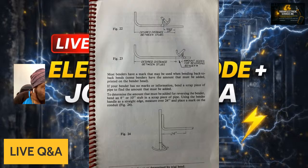Measure over 24 inches and place a mark on the conduit, figure 24. So again, it's basically telling you, most of us who've been bending conduit for years, on a simple offset, we can look at the bend that we need, the distance, and we can almost tell how much we need to bend. So a lot of times I can do that also, a simple box offset.